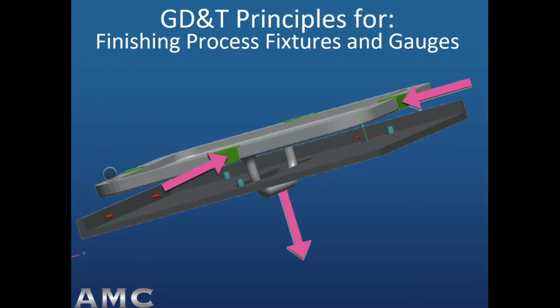So here we see the solid model, third generation solid model, poised above a generic fixture that represents gauges for processing and holding the casting for processing during finishing operations, straighten the casting after heat treatment, and ultimately these principles shown in this little generic fixture represent the machining fixture.